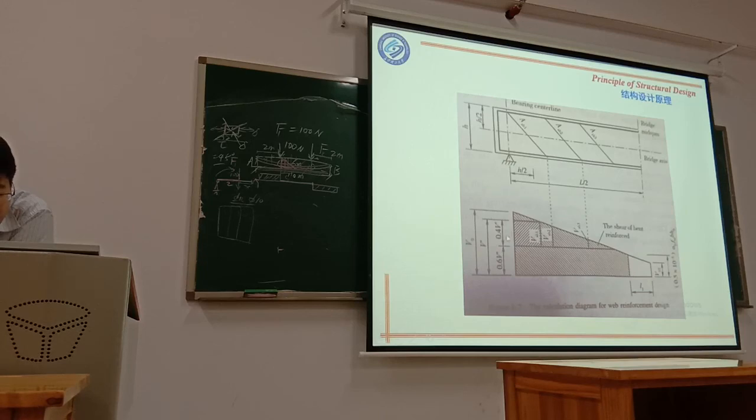This Vsb1 equal to 40% of this shear force. And at the first bend up point, the shear force Vsb2 is borne by the second bend up. We use this Vsb2 to design this second bend up reinforcement.